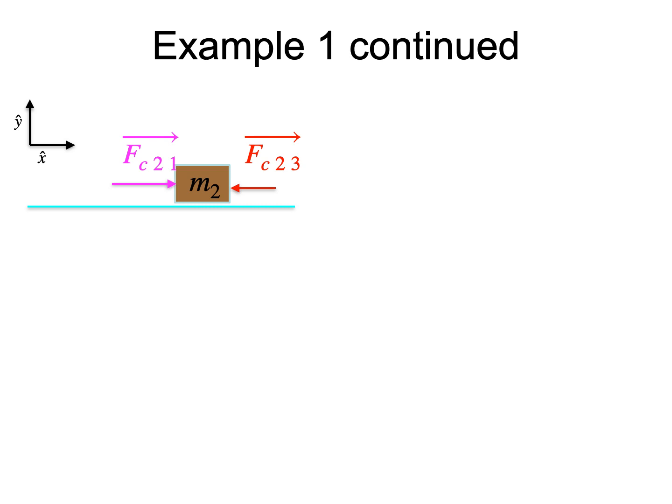Using Newton's second law would give one equation with 2 unknowns. We would need an equation to evaluate Fc21 as well. Not an impossible task. We just need to apply Newton's second law to mass 1 only to get that second equation. But let us look at a different approach.